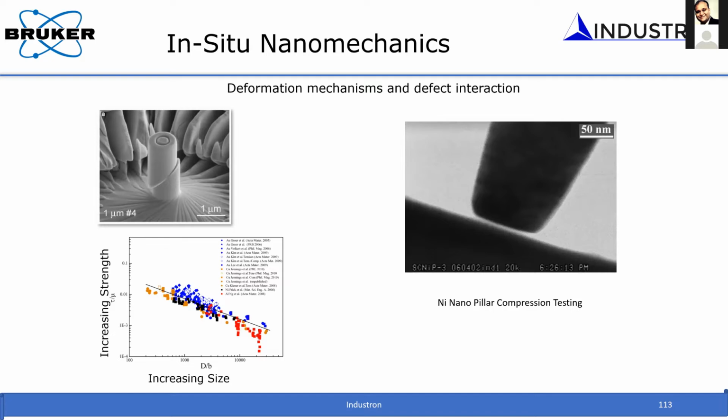We know that. And so there were a lot of theories at that time about why the strength of material goes up as it changes in the length scale, when it becomes smaller. So we thought we may be able to look into this problem. Our postdoc, Z.W. Shan, was able to FIB nickel pillars. And when you do the FIBing, the FIB process introduces a lot of dislocations, mostly toward the skin, closer to the surface.